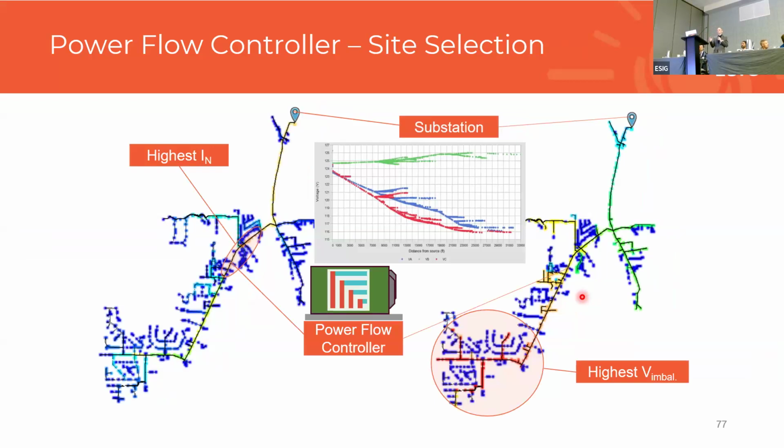So looking at that, you can see that for this particular substation, the phase voltage is really fanned out. And on the left, we still see that voltage profile. It kind of got worse, worse, worse, worse. And then it declined a little bit because we peeled off enough power that the flows began looking a little bit more balanced. And you'll see that sometimes.